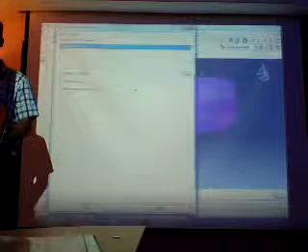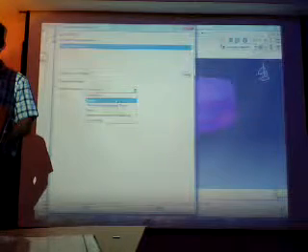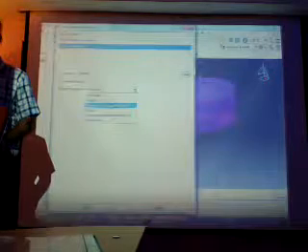You can see different formulations: frictionless, penalty, kinematic, exponential decay, and another one. For metal forming, normally we take the penalty one. Take penalty. Here you can see the friction coefficient, that's depending on your data. Here we are going to take it as 0.2.